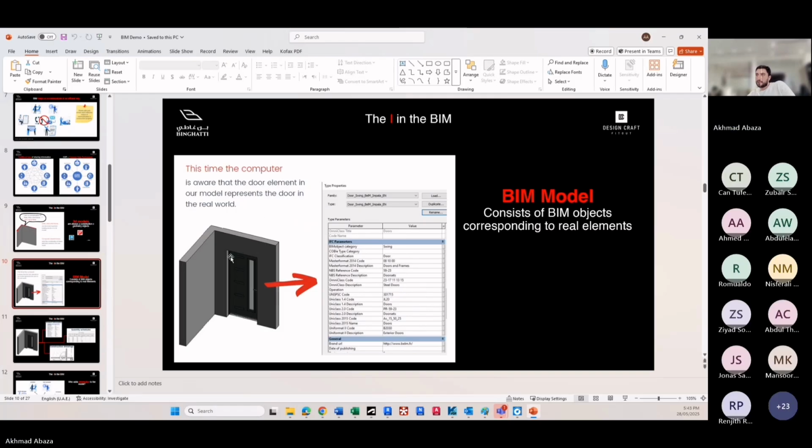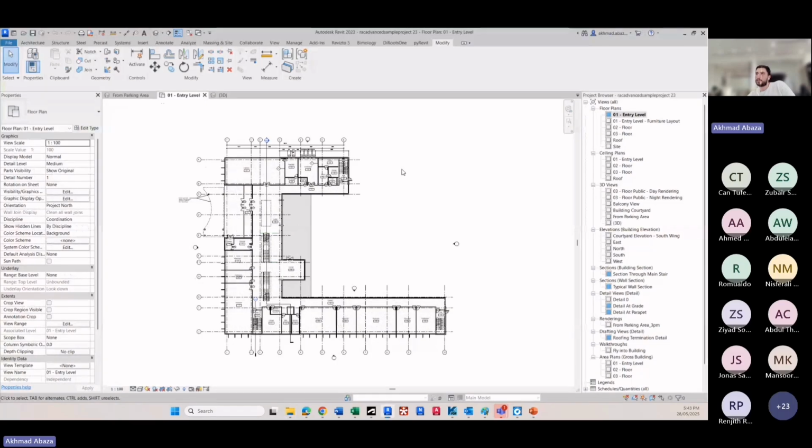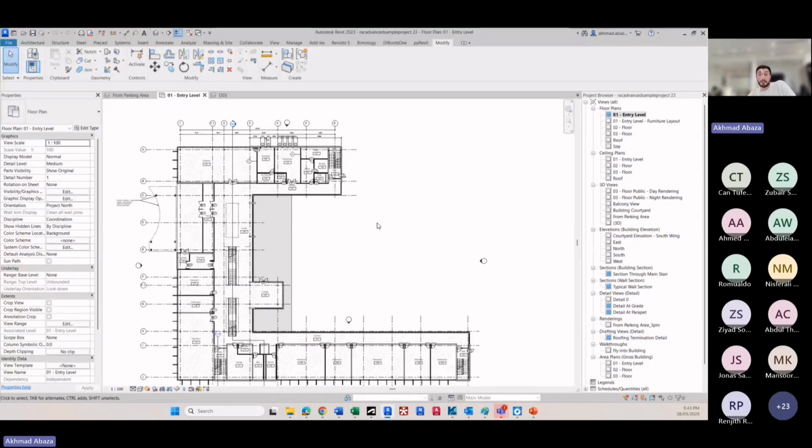However, in a Revit model, it understands the category. So, for example, if you want to select a group that is linked in this model but it is a SketchUp model, you cannot use the filter option because it cannot recognize the categories. Okay, all right, engineer, thank you. Later in the course, we will speak more about the filter and the advanced filter options we can have in visibility and graphics, and a lot of things.